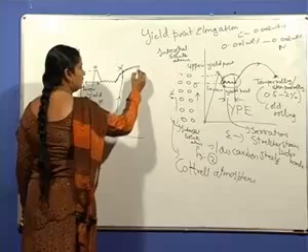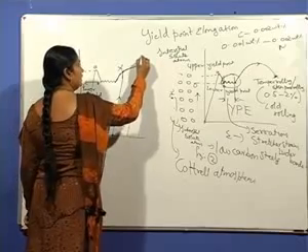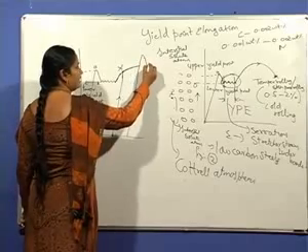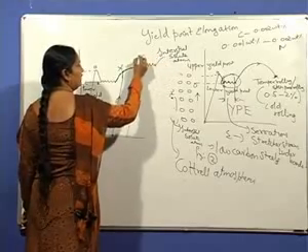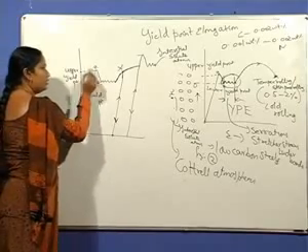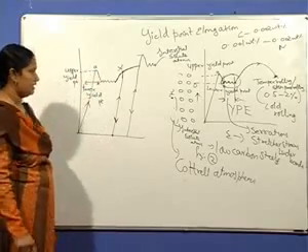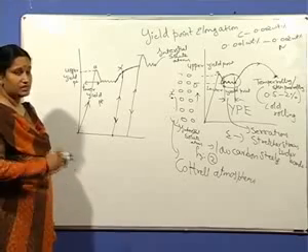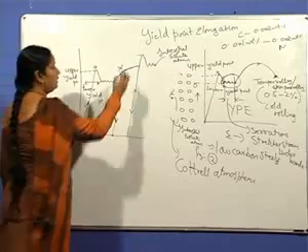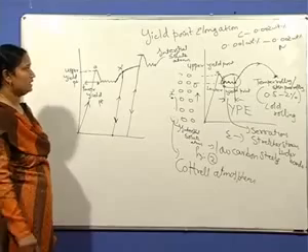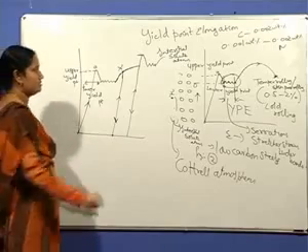Upon reloading, you see the reappearance of the yield point at a slightly higher value of stress. Initially the material yielded at point A, but when you reload it after several days, the yield point phenomenon reappears at slightly higher stress.